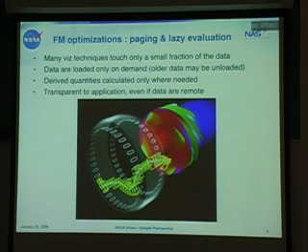I mentioned earlier that we also support derived fields. Typical computational fluid dynamics will calculate a momentum variable and two thermodynamic state variables. There's lots of other variables that scientists are interested in, for example, pressure or temperature. These are all derived quantities. So you have to pull the appropriate primitive variables and then run them through a transformation formula, and we'll only do that where needed. Many data stream or data flow utilities will actually calculate these derived quantities across the whole domain just in case you need them somewhere. We'll only do that where needed.